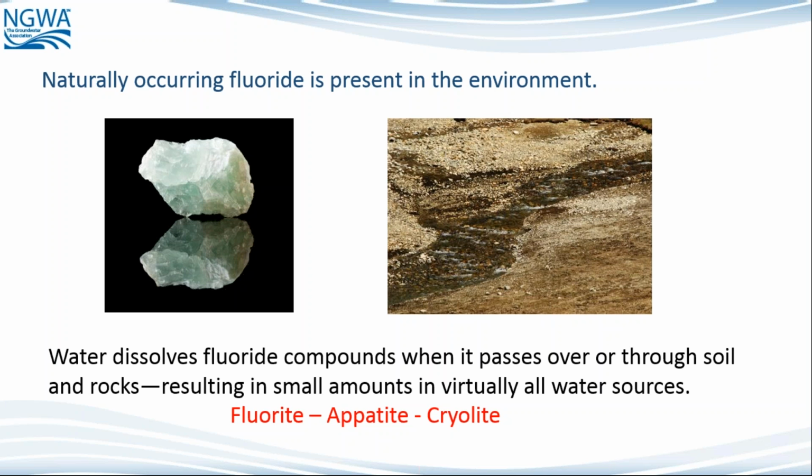Ironically, for fluoride, it is known that when the water is what we call alkaline, or a little higher in its pH value, the water has a higher tendency to solubilize fluoride out of the minerals that might be present in the geological formation. Ironically, I say, because in most situations it would be more of an acidic water, or a lower pH water, that would normally dissolve minerals out and provide that mineral in our water supply. Fluoride's a little different. Alkaline water, a little higher pH water, is actually produced a little easier in those types of water chemistries.